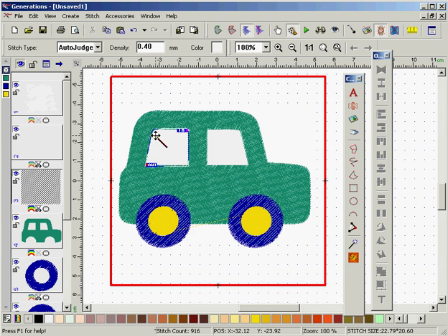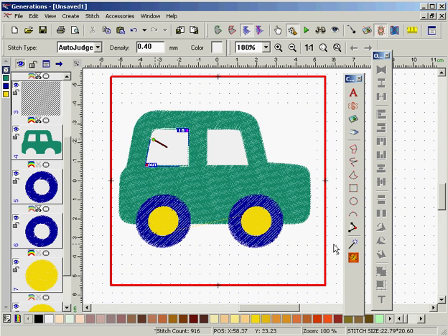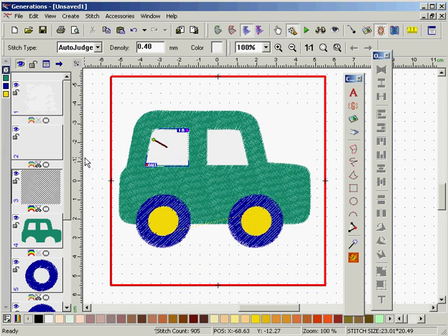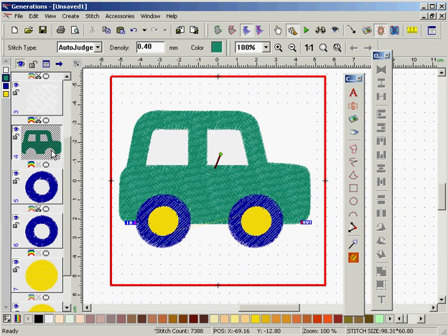Again, that's set at 45 degrees. I'm just going to move it off a fraction and click OK and generate. Okay, now we're going to machine out those two windows. I'm going to actually right click and move to bottom,